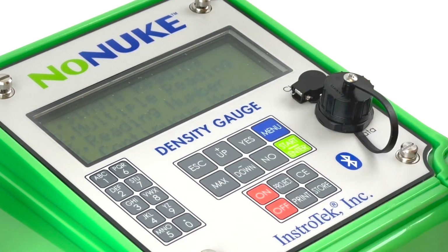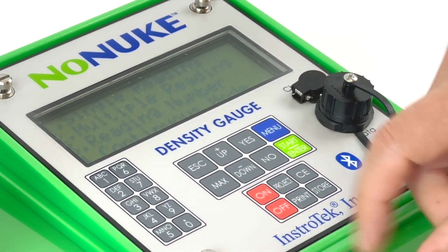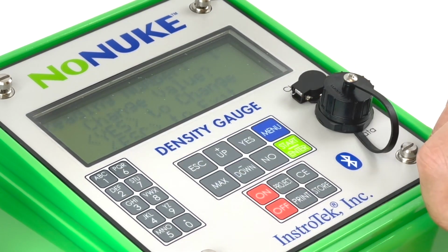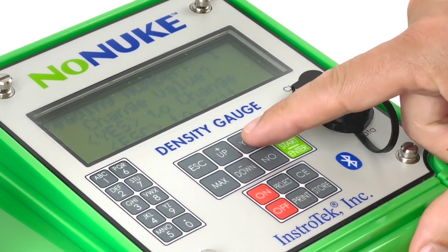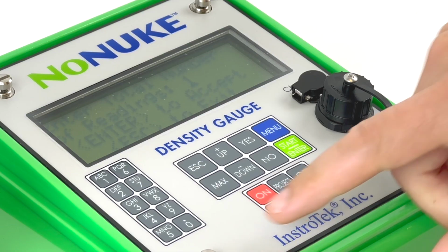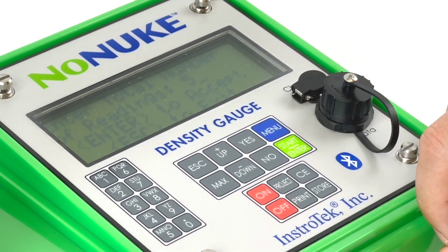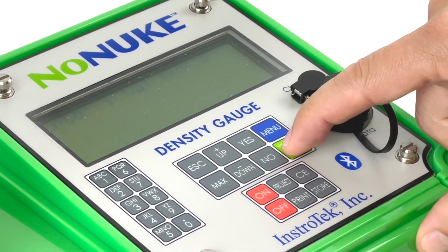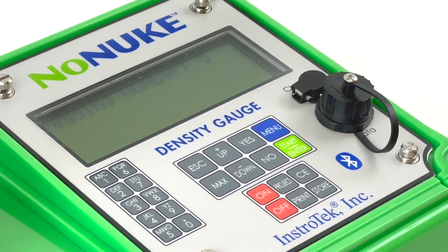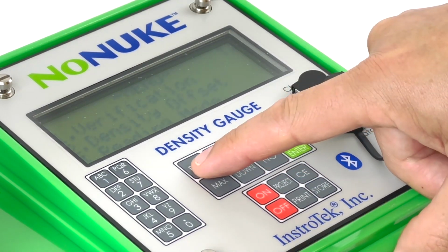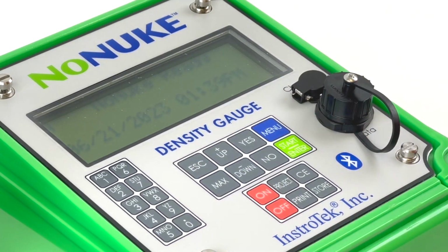To change the total numbers to average, select 3, Reading Numbers. Press 3 to review and/or change the reading numbers averaged in multiple readings mode. To change the total number of readings, press Yes and enter the new number of readings to average for each location. Press Escape to exit the reading number screen when the correct number of readings is entered. Press Escape again to leave the menu screens and return to the Ready screen.